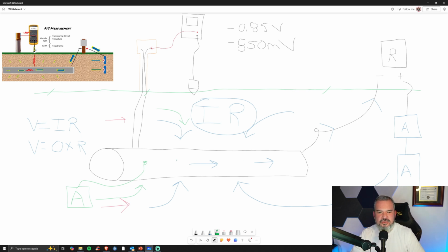Okay, well, let's say we dig those up and we cut those out. Let's pretend that our pipe system is actually connected. It ties in at a compressor station. And that compressor station has a very sophisticated grounding system. And let's say that grounding system is copper. If you go to my galvanic series video, you'll know that copper is more noble than steel. In other words, steel is more active than copper. The more active metal is going to corrode, produce current, to protect the more noble metal. And so if I turn my blue current off, my red current off, I don't have green current anymore.